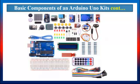The maximum voltage our Arduino Uno can tolerate is roughly 5 volts. But our AC ranges from 220 and above, or let's say 240, as the case might be in Nigeria. So you see, if you connect that directly to your board, it will just destroy it.